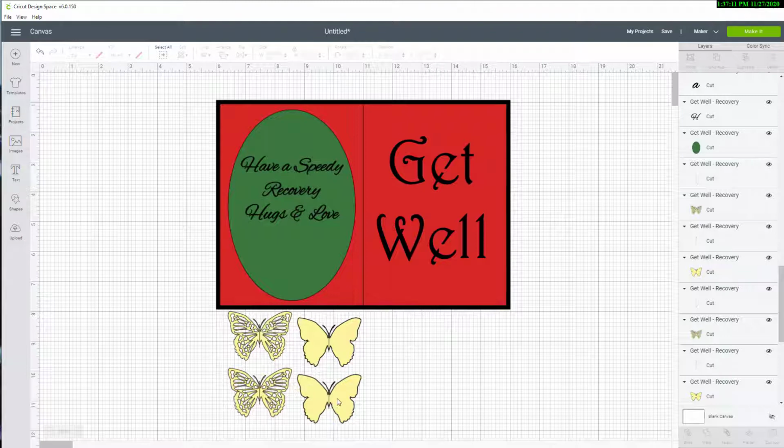So what I need to do is actually pick on those lines in the center. I'm going to shift click to pick the next one, and this is because it's SVG, and I have other lines in the middle here. Now if you have a hard time picking them, you can come over here and you can actually see them. I'm holding the shift key down, and instead of cut lines, we need to make those four lines score lines. Hey, that's perfect.